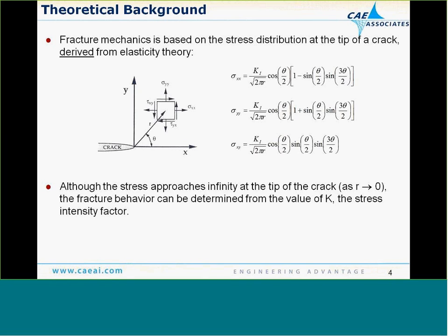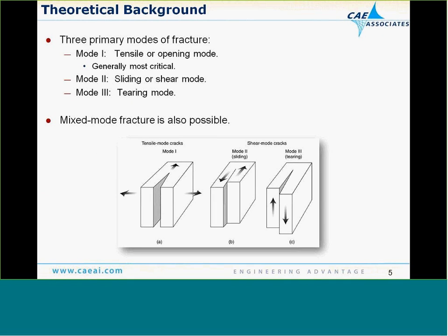That is a function of the crack geometry and the applied loading, and that stress intensity factor is the key in linear elastic fracture mechanics. We can compare that to the fracture toughness of the material to determine if the crack will propagate. So we're accepting the fact that the stresses are infinite at the crack tip, but we're using the derived expressions to calculate this stress intensity factor. Notice that there are 3 different modes, and you can calculate 3 different stress intensity factors at a crack tip.